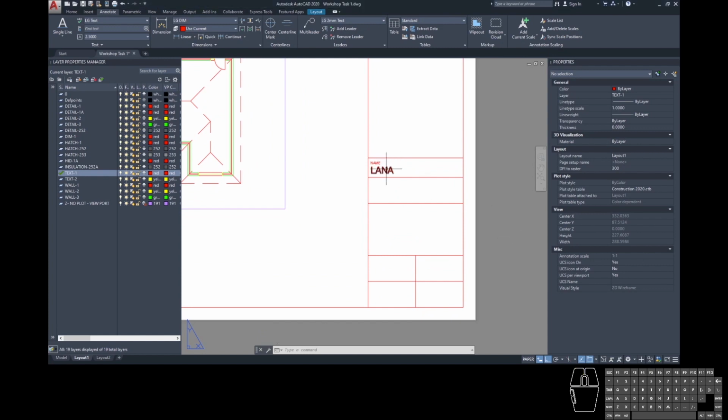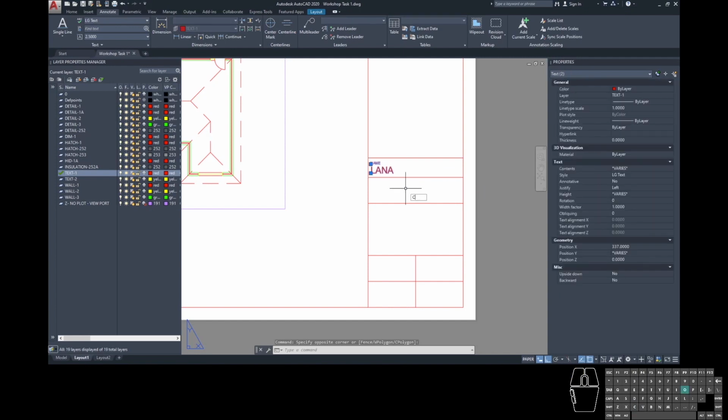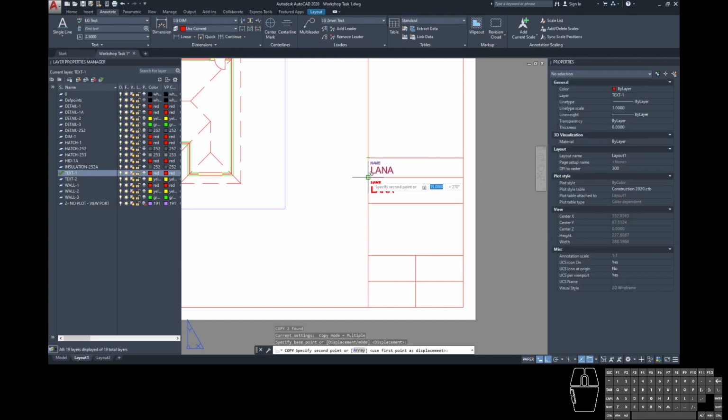Now that I've got that first set of title filled out, I'm going to copy that again. And if you copy it and you're using O-snaps, it means that this will sit in exactly the same place within each section. And then you can just go in and refill each of these with the required things that are in that original title block. As you can see here, all of this text is specific to this page, so as we would have for our original hand drawing, it's now sheet title plan, it's 1 to 100, it's sheet number 1.